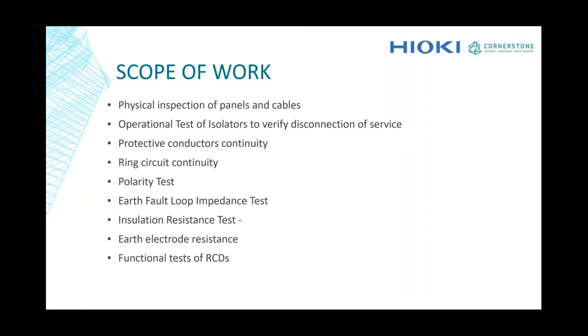The first one is the protective conductors continuity test. Here we need to verify earth continuity from equipment and accessories that are connected in circuits.